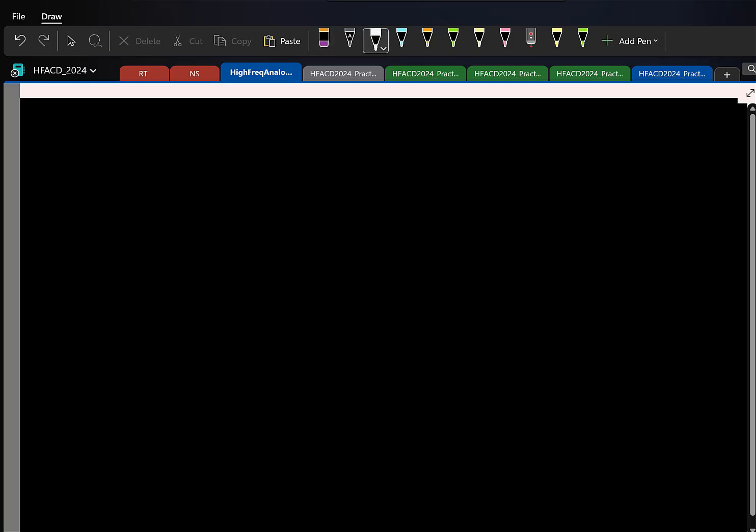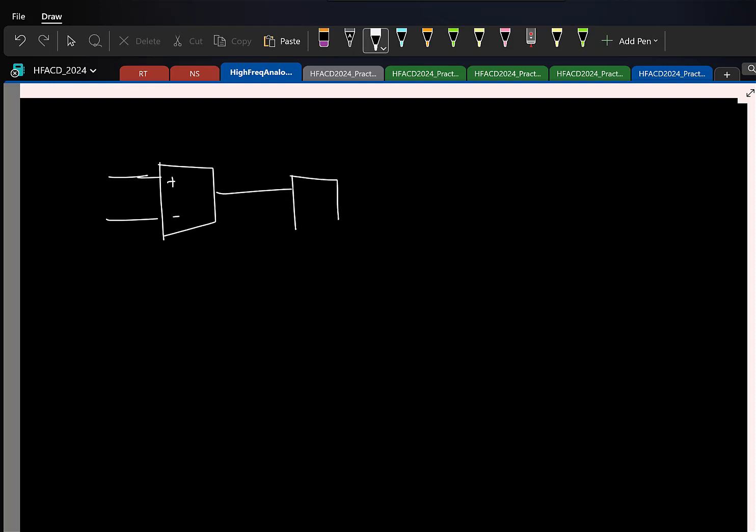So again, I'll draw it at a block level. So let us say we have a 2-stage, first stage, second stage like this. And as you know, to compensate this, we saw a couple of techniques. One was Miller and feed forward. So for Miller, you added this cap and stuff. But for noise calculations, we'll ignore frequency dependencies because that will complicate calculations. So we'll only look at low frequency noise, right?